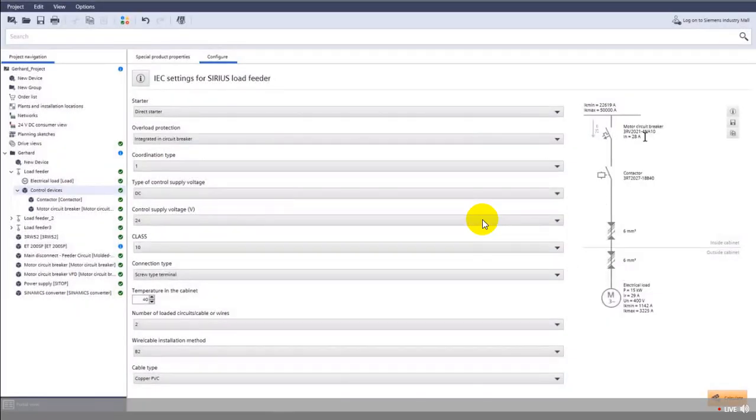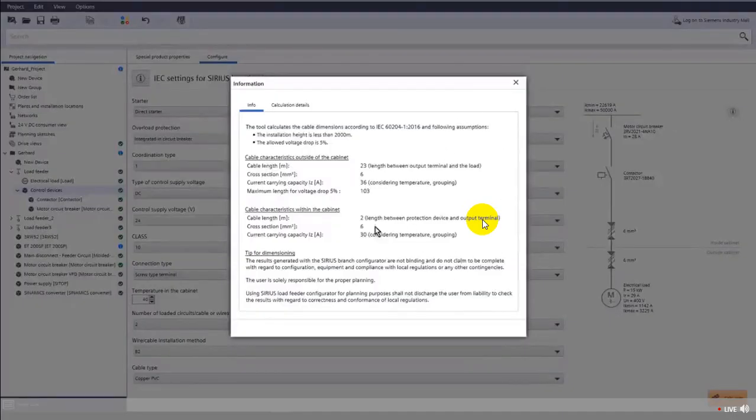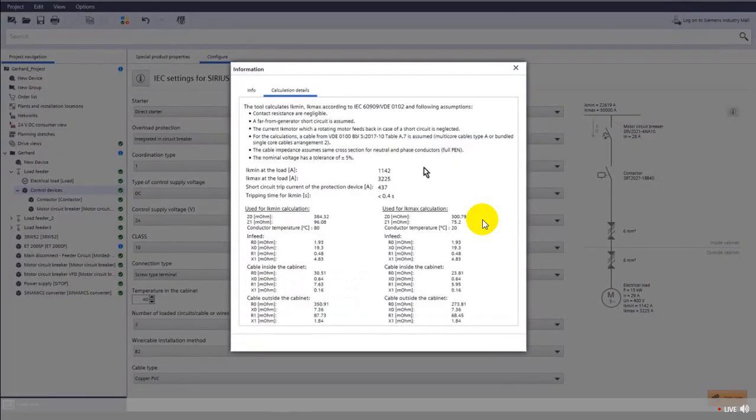And as you can see here, we have again the resizing of the starter and also the dimensioning of the cable. Yeah, of course, more power, we need a larger cable for this type. Oh, wow, that's it? Yeah, that's it. Easy, right? That's simple and that fast, and you will have the opportunity once again to have everything for the documentation, and also something that I didn't show you before, the calculation behind everything, with the impedances and basically the type of load and cables you're using. Awesome. That's very helpful for my technical documentation too.